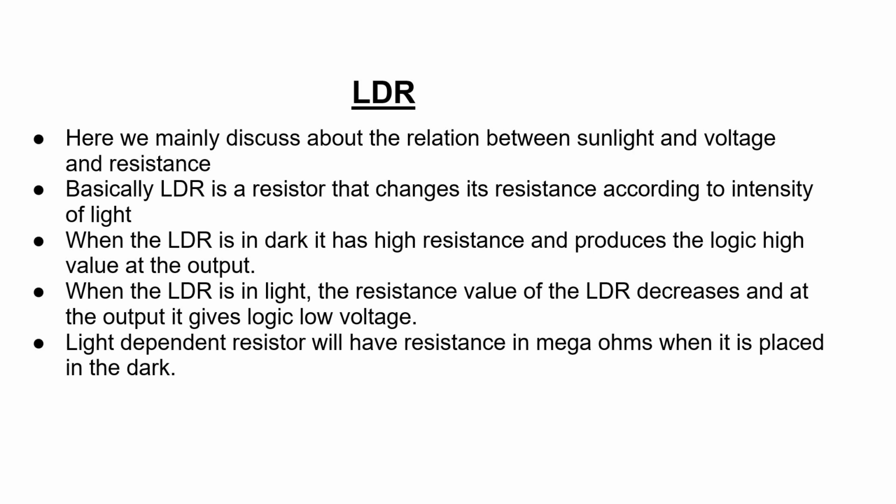The key objective is to reduce manual operation and energy wastage by enabling lights to turn on only at night and off during the day. This automation relies on the photoconductive property of the LDR. Its resistance decreases as the surrounding light increases.